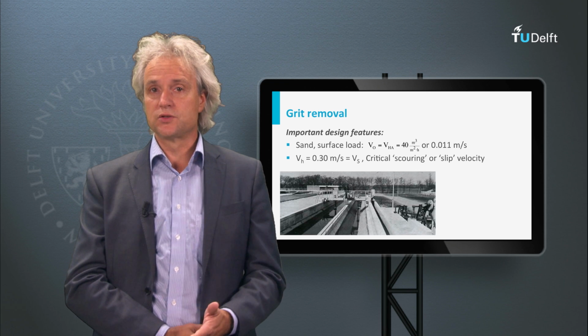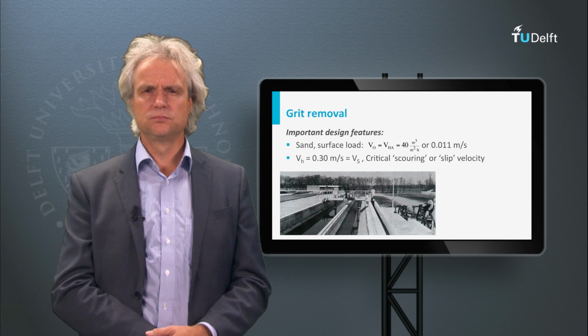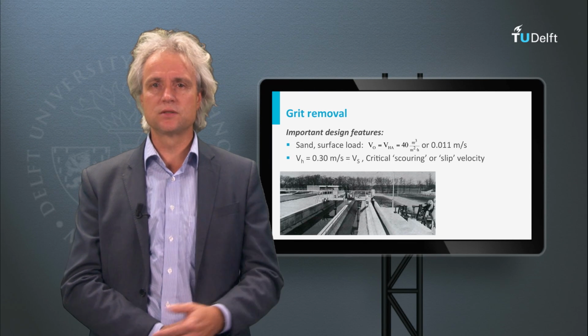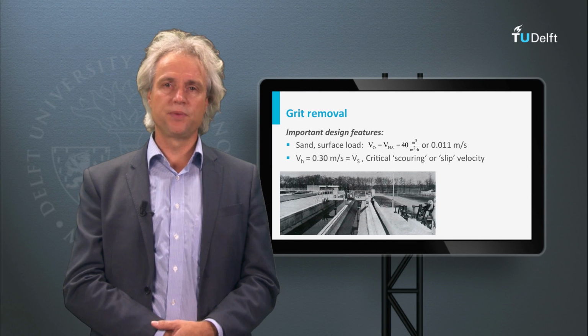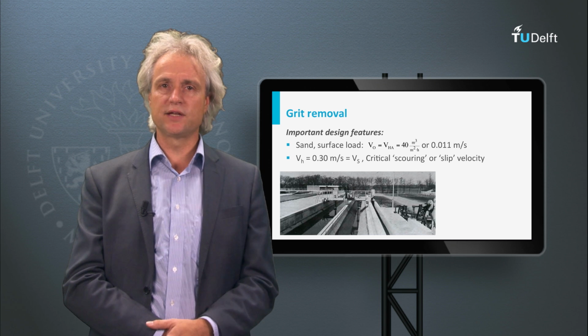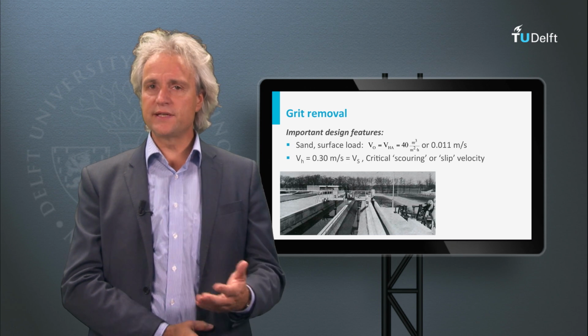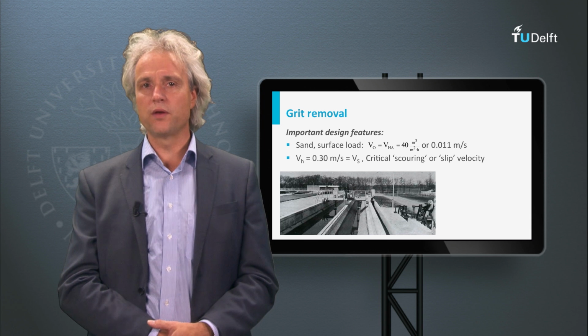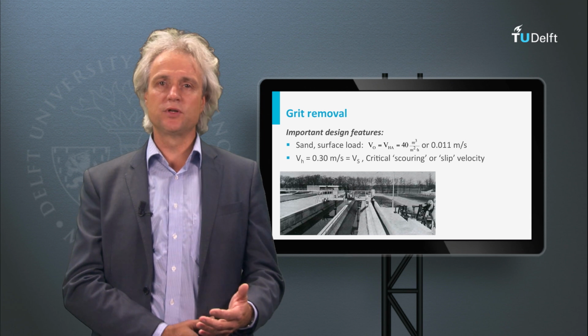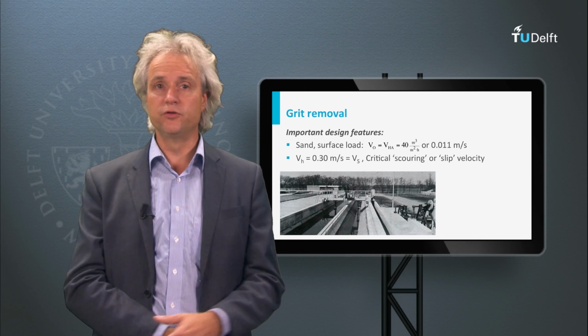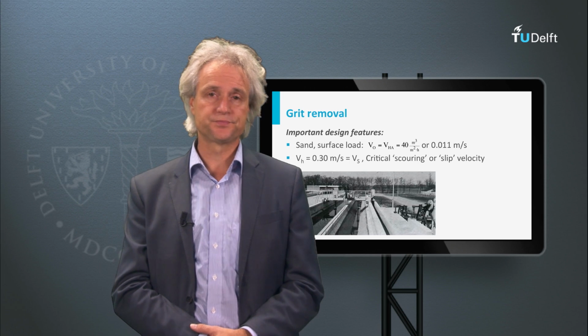purposes, like construction works. How much sand will be recovered at an average STP? This will depend on the type of the sewerage applied, the extent of the sewer network, and size of the area served. For STPs treating the sewage of more than 100,000 inhabitants, the sand production is about 2 to 12 liters per person per year. So, a few containers per week.